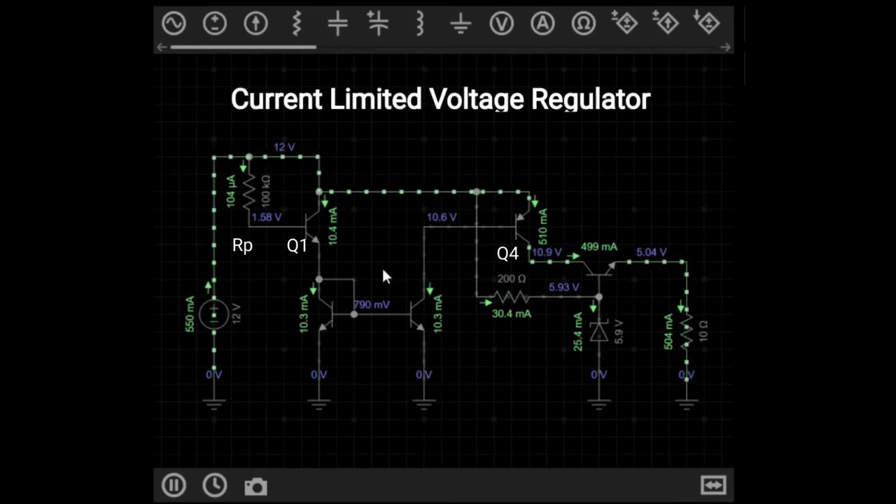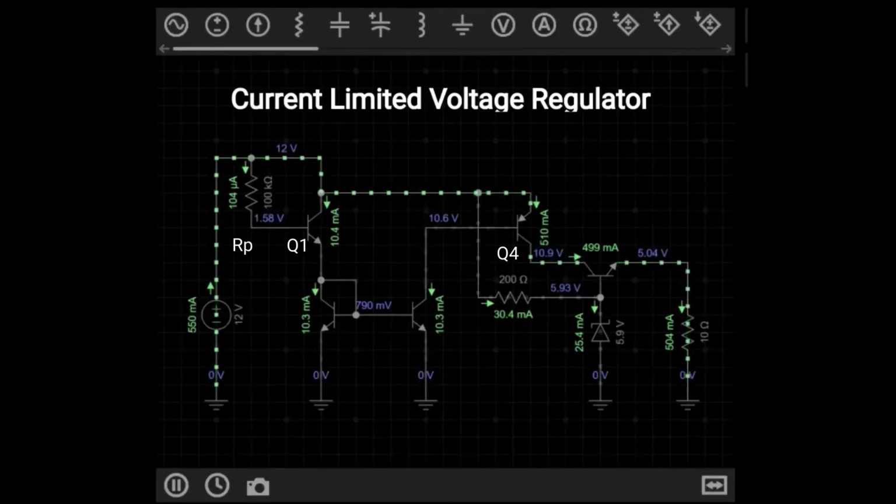You also might notice that this version employs a current reference buffer here. This transistor allows you to, based on the beta of this transistor, set the supply's output current by supplying a current in the order of microamps. This could be achieved by using a microcontroller and a D-to-A converter.